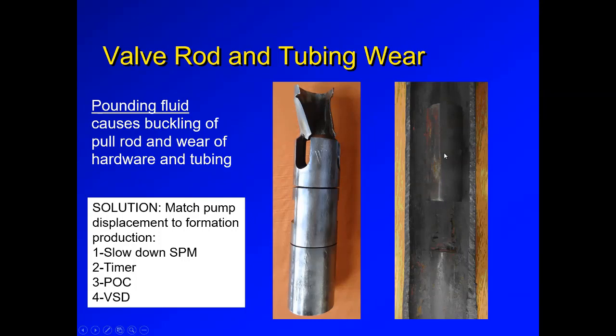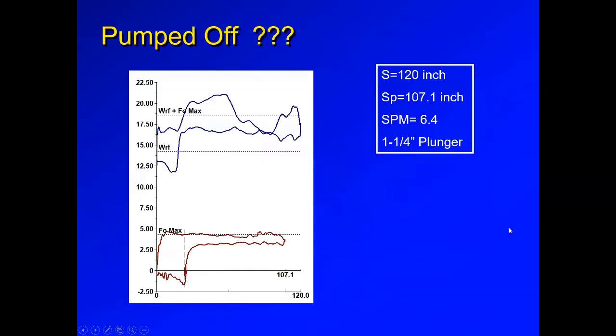So it's very obvious that this well has been having an incomplete pump fillage, a fluid pound condition, for a long time. This will eventually lead to either a parted rod or a hole in tubing. So that's why we don't want to pump the well in these conditions.